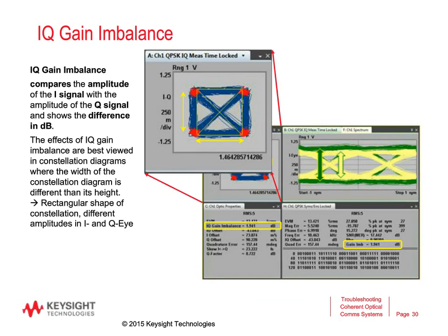Another measure that we look at, especially if we try to find the operating points for a modulator, is the gain imbalance. It basically compares the horizontal, the I, and the vertical Q amplitudes. And we come to the conclusion here on this picture that obviously the horizontal amplitude is slightly higher than the vertical one on the constellation.